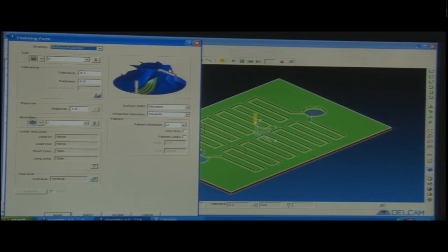Now, what is there? You can see the tool in 2 directions here. Here the tool is in horizontal direction and the tool is also in vertical direction. So, this is surface projection. How does surface projection happen? This can only happen when we have at least a 3 plus 1 axis machine.